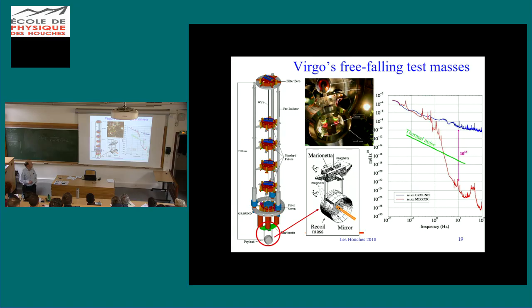Here is the fabulously well engineered Virgo super attenuator, and this has one very low frequency oscillator in the inverted pendulum stage. That's this as a mass on a spring represented by towers that have some elasticity down here. And now a chain of 1, 2, 3, 4, 5, 6 or 7 pendulums. How do we count them? Yeah, well, yes, here is the inverted pendulum. I get that. So regular pendulum, 1, 2, 3, 4, 5. And is this part rigidly attached to that? I'm not sure. So about six stages.